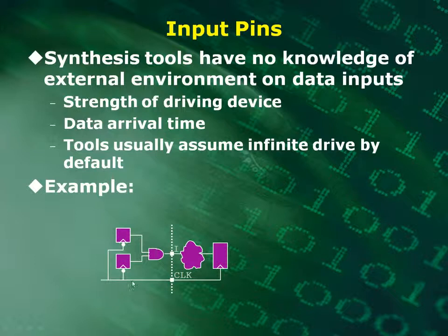It's being driven by this clock, and so is this internal logic. However, in order to calculate everything from this clock to this clock, it doesn't have a lot of this information like clock to Q, and then the delay of this external logic you have. And so it's going to need to know some information here so that it can meet your timing analysis about your inputs. Okay, because you may have some more logic in here before it gets to the flip-flop.